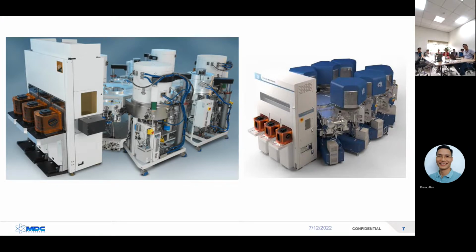So that one would probably be somewhere underneath here. And then you have this turbo pump. This pump is pulling down to vacuum. Then there's a line from this turbo pump that goes all the way down below this floor. In a fab, there's a whole other basement where the main pump areas are. So this is the pump that takes it down to super high vacuum, but then that pump is being pulled by another pump down in the basement. So all that line we do.